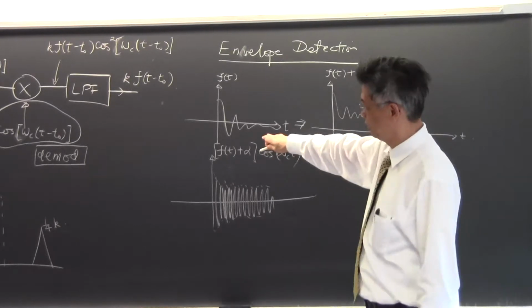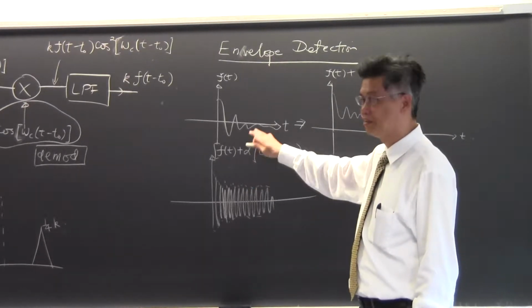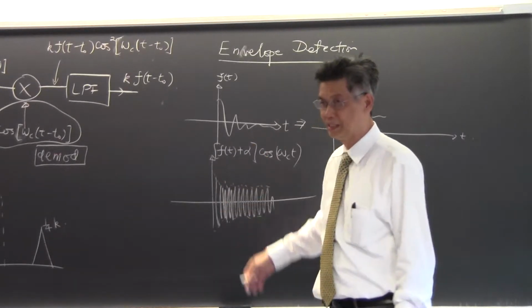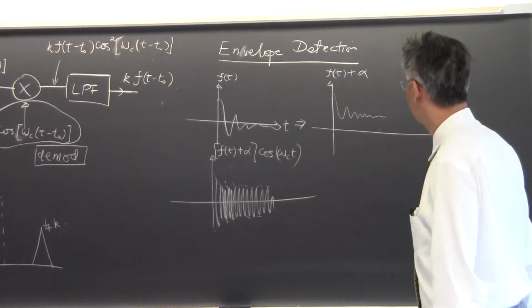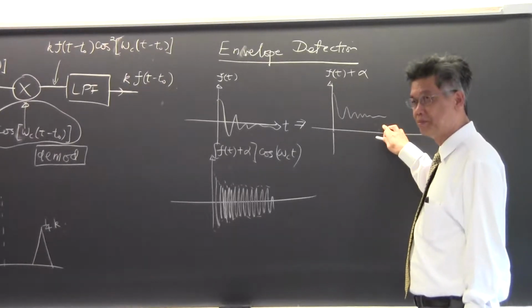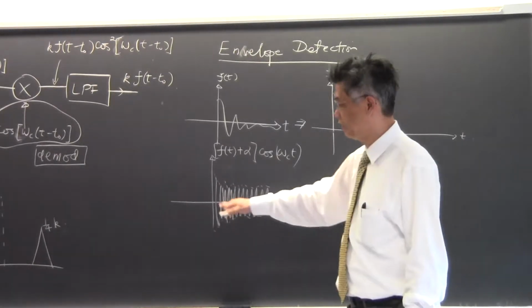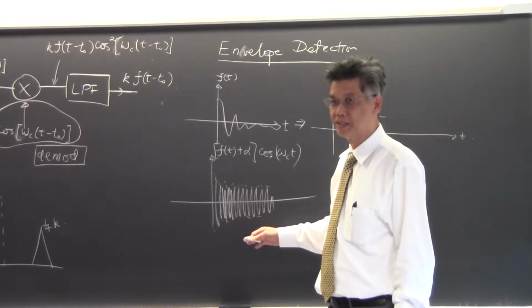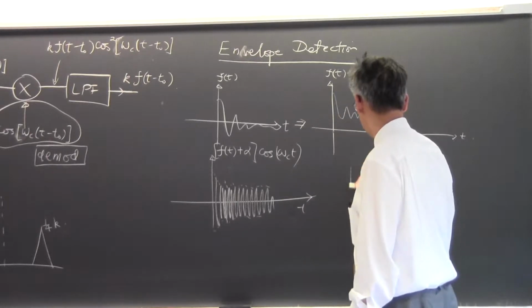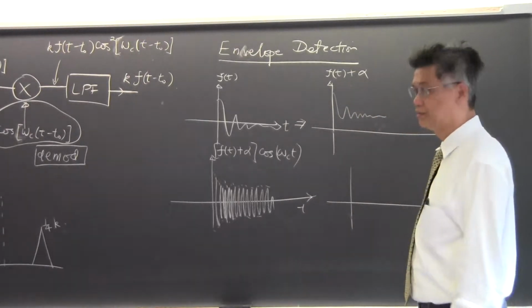Whereas if you were to modulate the thing directly, you will have some sign confusion. Something will turn negative and something will turn positive. But if I have it modulated this way, I know that my signal is always having a positive sign. Any negative signs that I have come from the cosine signal. So I can do a detection. There are two ways to do the detection.